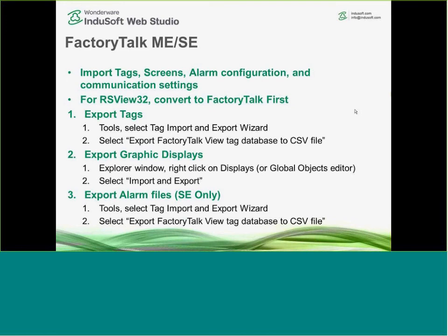So the next one I'm going to cover here is FactoryTalk. So FactoryTalk View ME and SE screens can be brought in, and not only screens, but we can import tags, screens, alarm configurations, and communication settings.